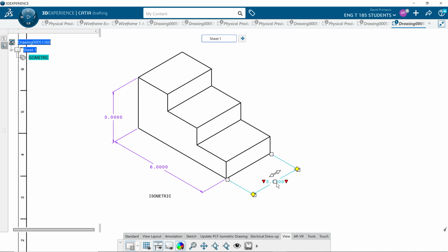And how I do that, select the red, put in a parenthesis, select this, select OK, select this red triangle, select parenthesis, and it's closed. The other technique would be to click on this, click on that at end, and type in reference in capital letters, REF, for reference. You do one or the other, not both. This way would be legal. This means reference, and so do parentheses.